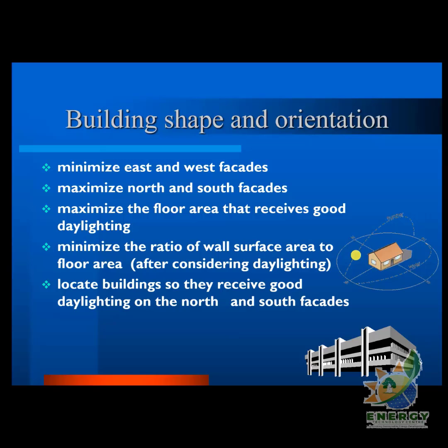So you normally would have an elongated building along the north-south direction, so that you make sure that you allow minimum amount of light to penetrate when the sun starts and when it sets. And when it's directly overhead, you can have the roof shading a lot of energy from the sun, because then the sun is directly overhead.